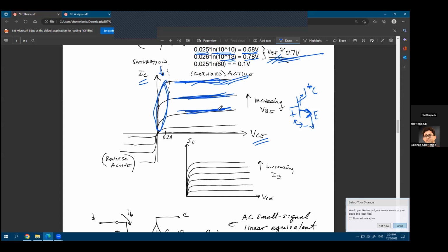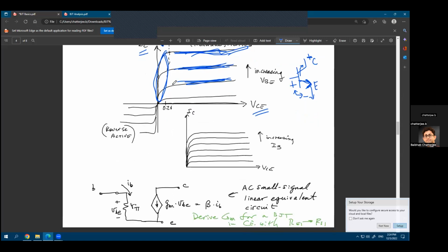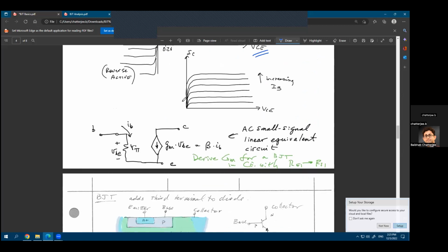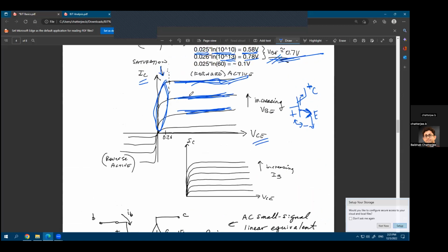So the saturation region is something that might get confusing to some of you, but keep in mind that they are defined for different terms. For MOSFETs, the saturation is defined as a saturation of current. For BJTs, the saturation is defined as a saturation of carriers. And that's why they sort of signify different regions of operation. Even though the curve looks exactly the same, the phenomena is sort of similar, and also the numbers that we'll be seeing are also very similar. But the naming convention has historically been different. Okay, so that's about your IC versus VC characteristic.